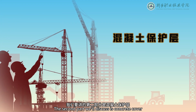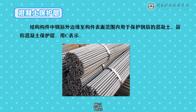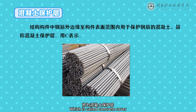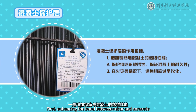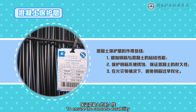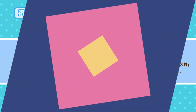The second part we'll discuss is concrete cover. The exposed rebars are prone to corrosion. Thus, rebars need a certain thickness of concrete protection, which is called concrete cover. Its functions include: first, enhancing the bond between rebar and concrete. Second, protecting rebars from corrosion to ensure the concrete durability. Third, preventing premature softening of rebars in case of fire incident.